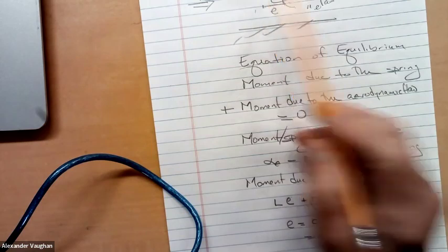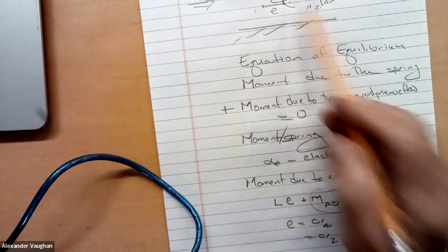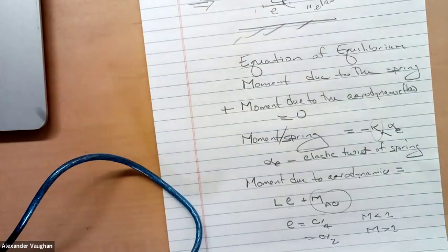So what I'm saying is, in low speed flow, this aerodynamic center is roughly the quarter chord. Of course, this spring point can be wherever we choose to attach the spring, right? And we'll see that E is really important in divergence. I mean, a lot of things are important, but E is certainly important.